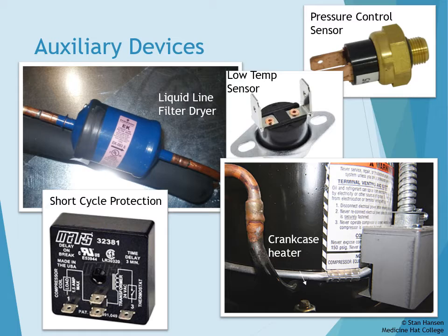And we have a low temperature sensor. The low temperature sensor shuts the system down if it is too cold outside, so the ambient temperature is lower than the evaporator temperature. We have short cycling protection, which stops frequent stop-starts in the system and also protects the system from starting when the pressure is too high.